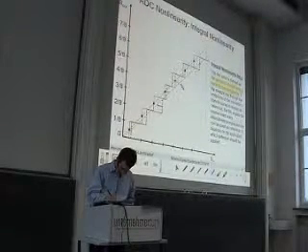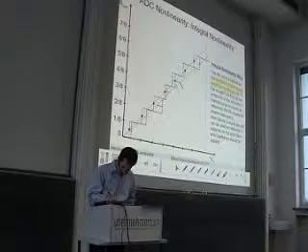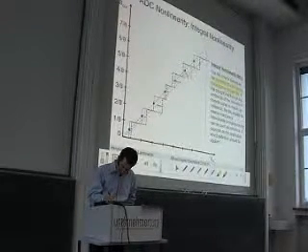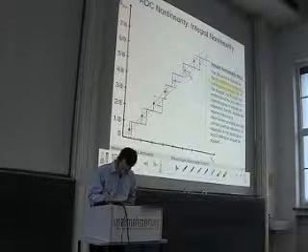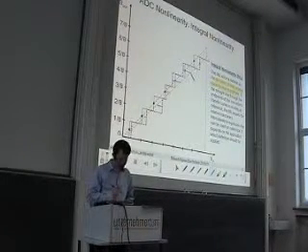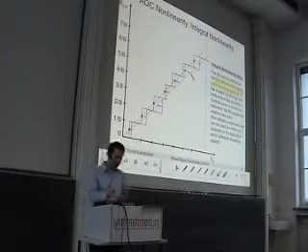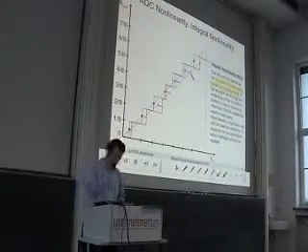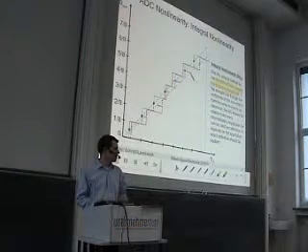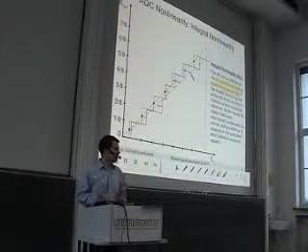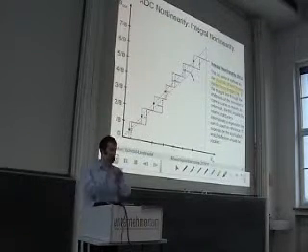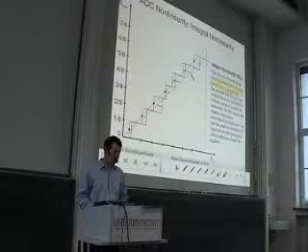Here it's a quite large one, or here. This is the integral nonlinearity. And then again, we can take all these values, plot them on an axis, and say, for this input value, we have this deviation from our straight line, and this is our integral nonlinearity. Or we can choose the maximum and give this as a single number.